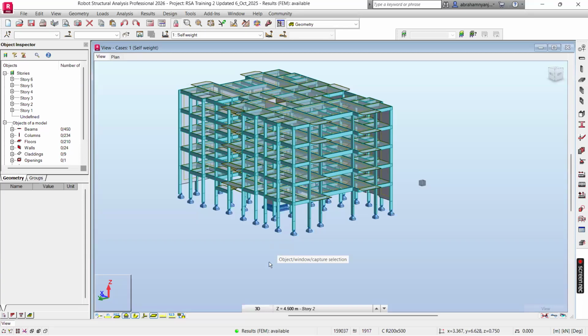If the structure is settling with all points settling at the same rate, that is okay. You will not have differential settlement. The only question would be how much will it settle? Otherwise, it might settle and you find doors turning into windows. But if it is settling at once, then that is okay, because then there are no other stresses, but still it shouldn't settle so much beyond what was anticipated.